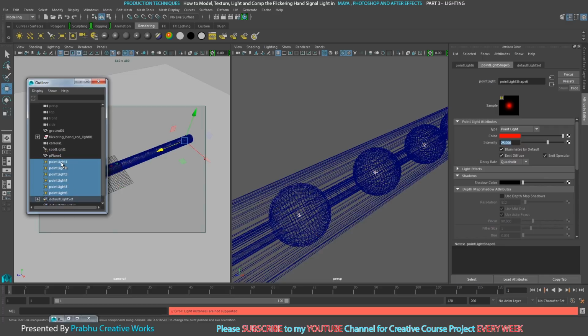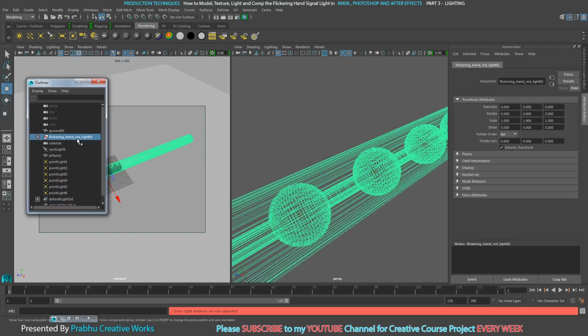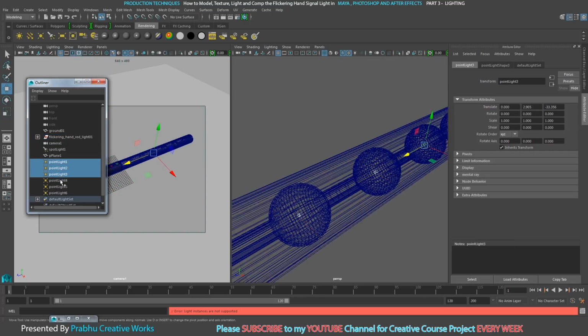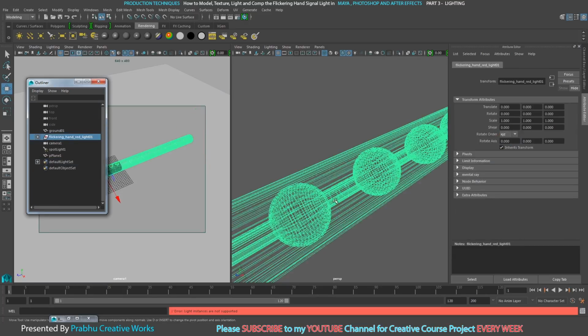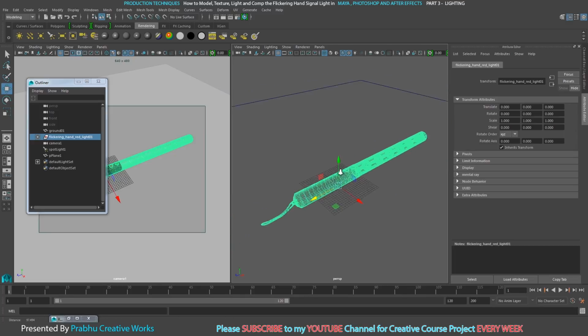select all point lights and Shift select your group. I select all point lights in my outliner, hold middle mouse button and drag to your group. So that means all the point lights go inside our group, so you will be able to select all lights and all objects in the same group.